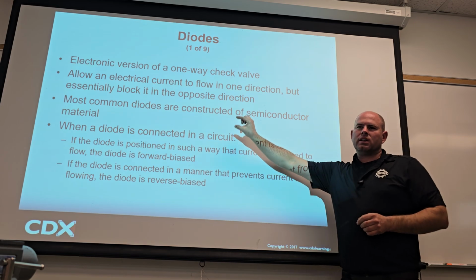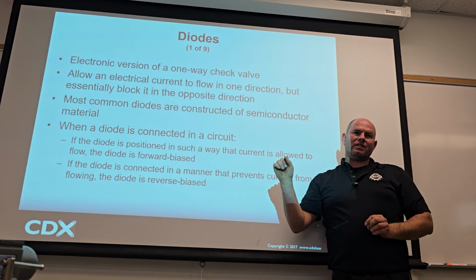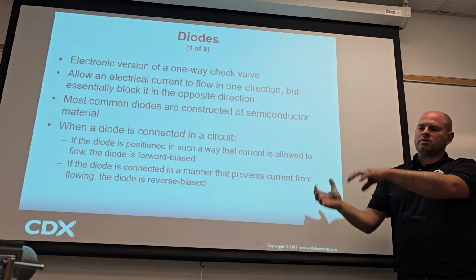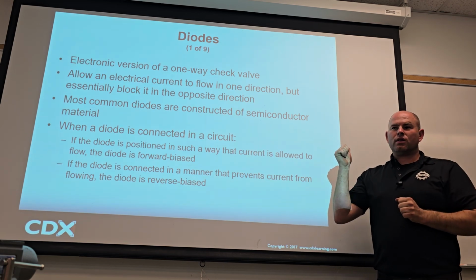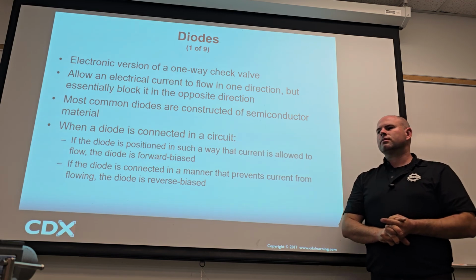Some diodes are actually external. Some diodes are in the ECU. So if it's in the ECU, we're probably not going to be able to test it quite to that level, but sometimes a diode's placed in the fuse box. There were diodes out here in the fuse boxes from our tests last week. I saw a few of them, so we could test those.